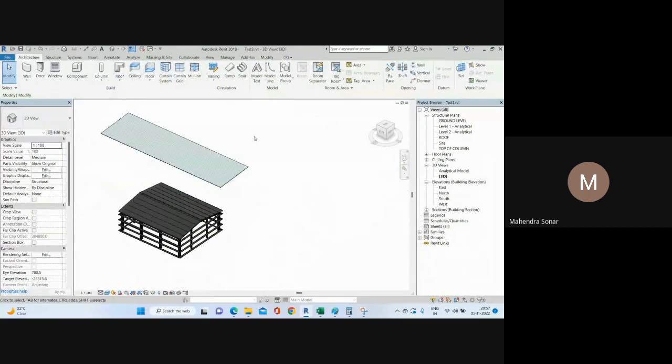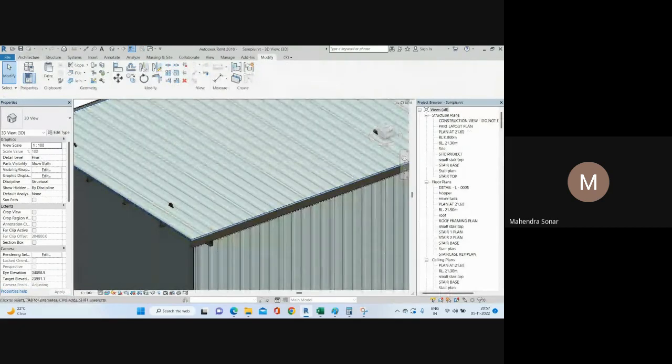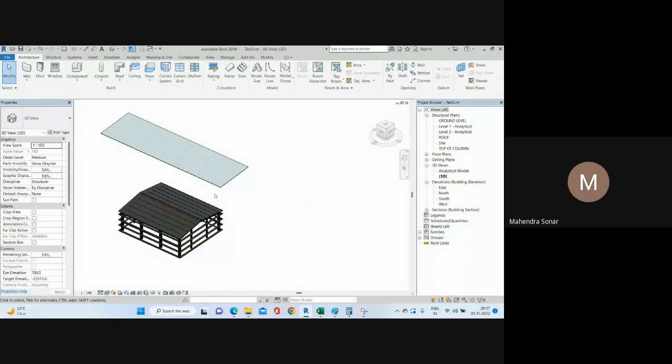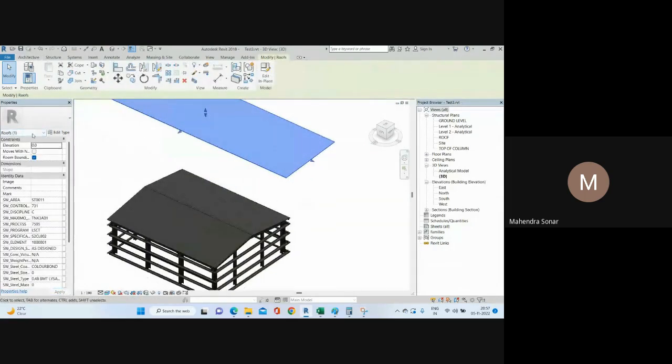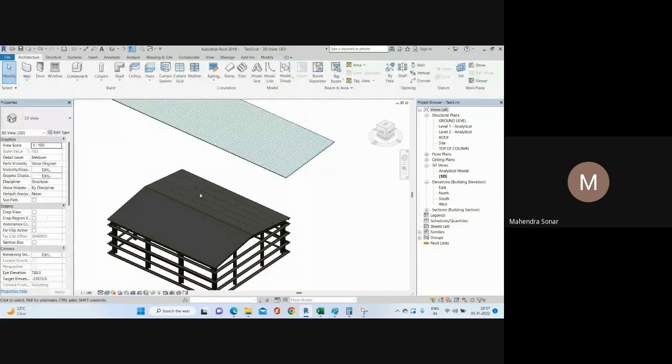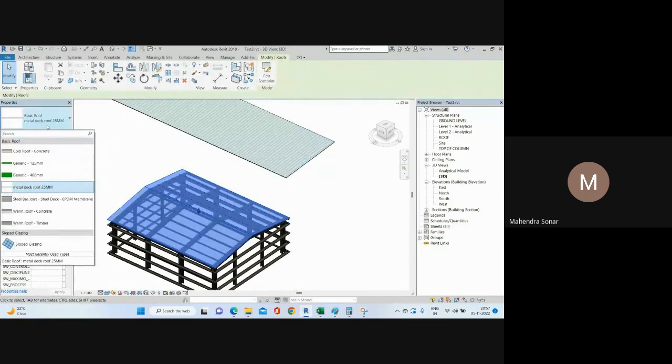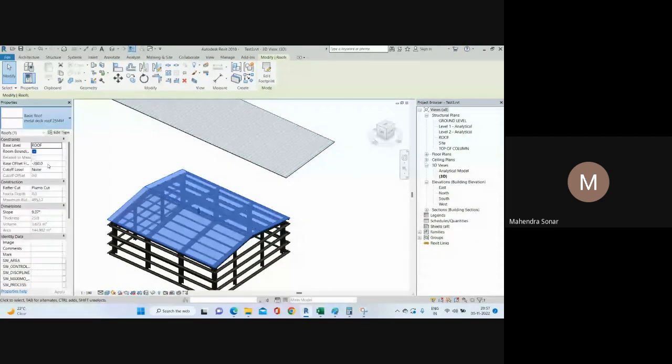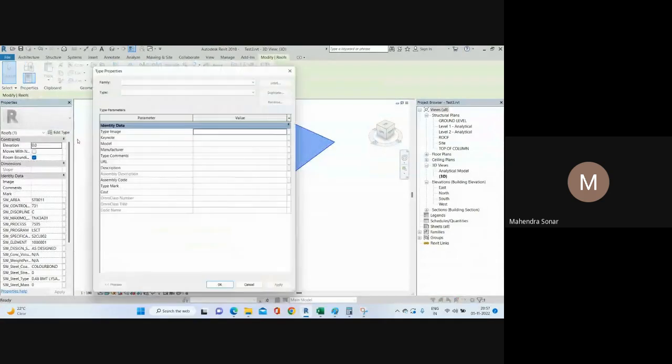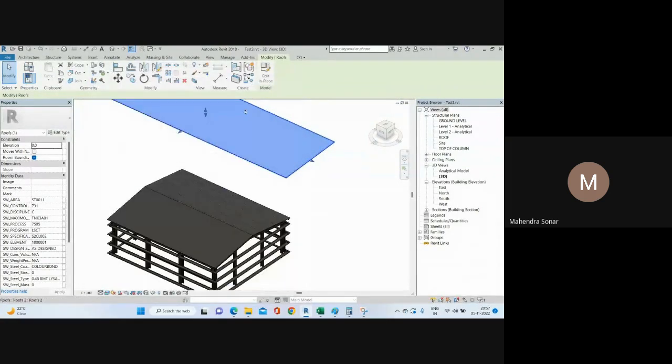Okay, so you can convert this, right? Close this file. Once you copy, you can see this family is coming here. So this is the roof, and if I go to edit, I will select this and see this family come here. If I check and go to edit type, oh, they have used edit in place for the roof.